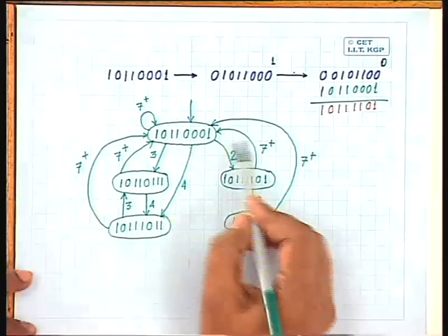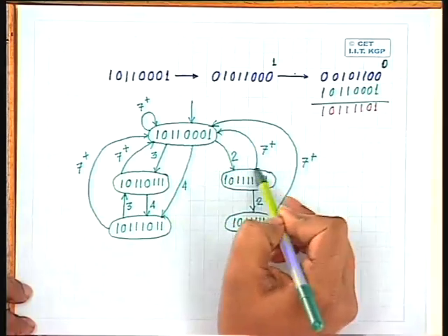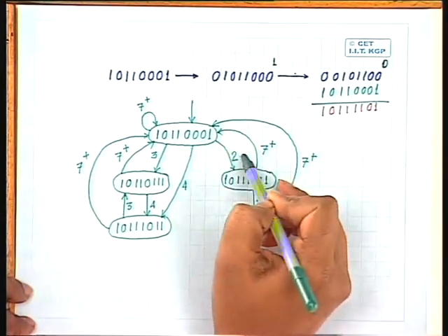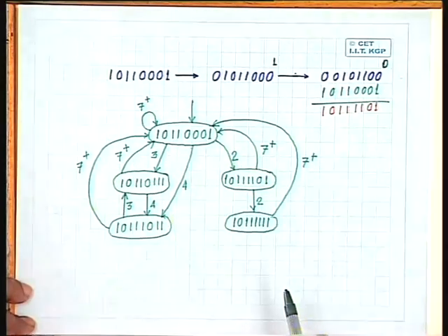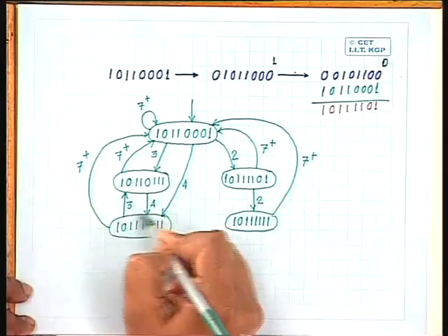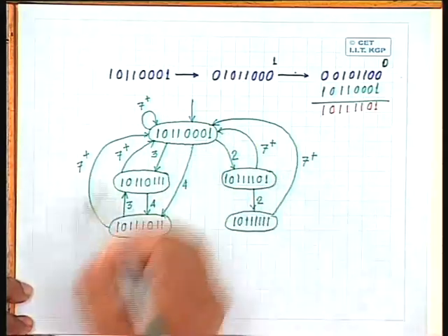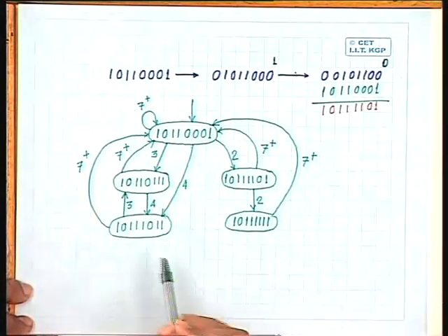So, if you do that, you find that if I take just this cycle, here the latency is 2 plus 7 or more, that means the minimum latency involved with this cycle is 9 divided by 2, so the average latency is 4.5. If I come here, 4 plus 3, 7 divided by 2, that is 3.5. And you will find that the minimum average latency for any cycle that you get in this is 3.5.